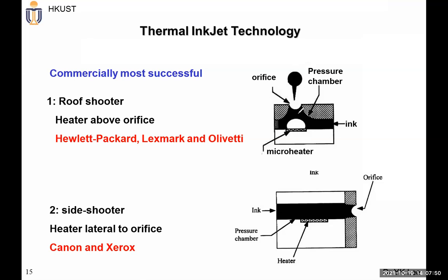That's why this is something unique in microfluidics. So we leverage this kind of special phenomenon at micro scale, right? It's micro heat transfer, micro boiling heat transfer, and then create some interesting repeatable micro bubble to use as a pump to push ink out of the nozzle.